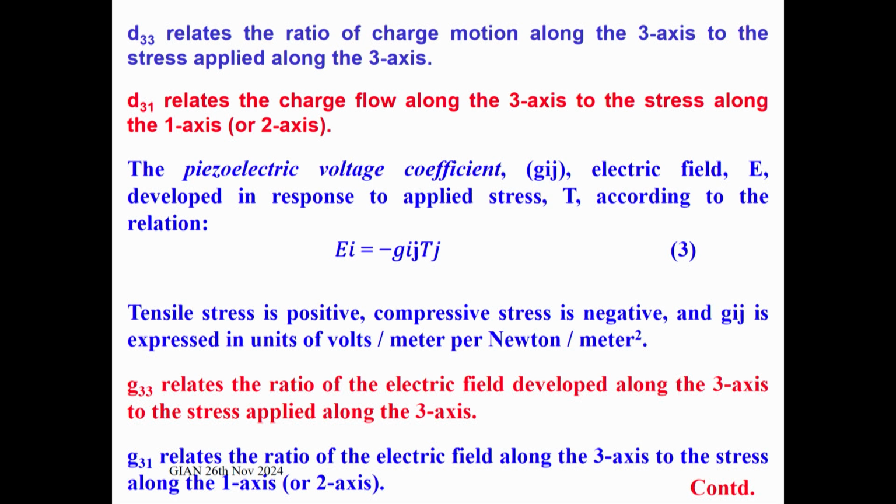So, here you are interested in how much charge is accumulated along a particular direction as a function of applied stress. The other term which is important from the application point of view is the piezoelectric voltage coefficient. The piezoelectric voltage coefficient is the electric field developed in response to applied stress. So, the polarization or accumulation of charges is measured in terms of voltage, the polarization accumulated in a particular direction.